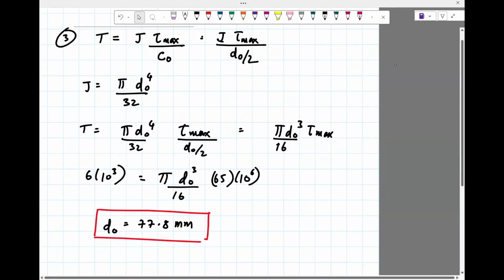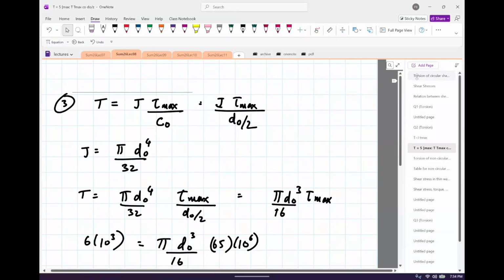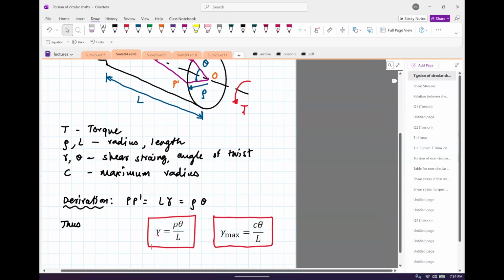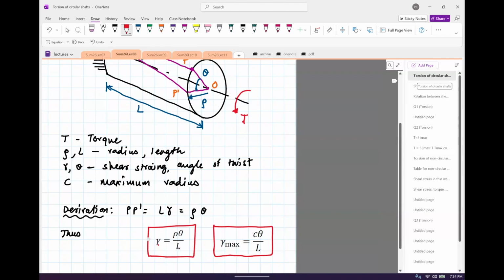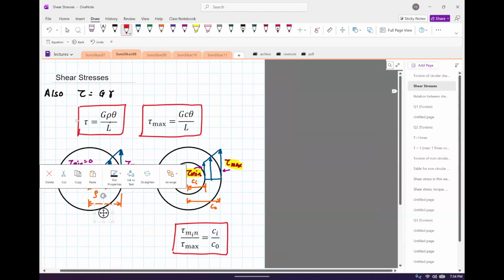Normally we had another problem we talked about, normal stress and shear stress. So the question: doesn't the length play a role? The length plays a role only in the shear strain and not in the shear stress. If you look at the formula, the shear strain depends on the length, but it's not the torque. Now you could say that shear stress comes from the shear strain, and there the length factors in.